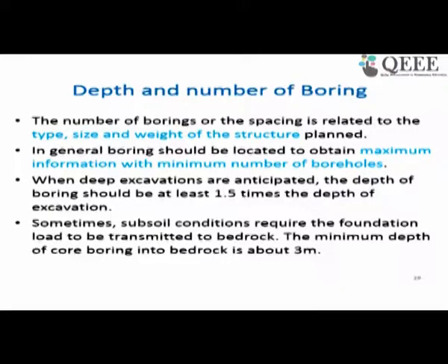When deep excavations are required, the depth of boring should be at least 1.5 times the excavation depth. Suppose you have to excavate 10 meters, then the borehole should be at least 15 meters. Sometimes subsoil conditions require more boreholes. If there is bedrock or some difficult conditions, it has to go much beyond the layer where you anticipate some kind of problem. Usually if bedrock is there, going beyond 3 meters into the bedrock is good enough.